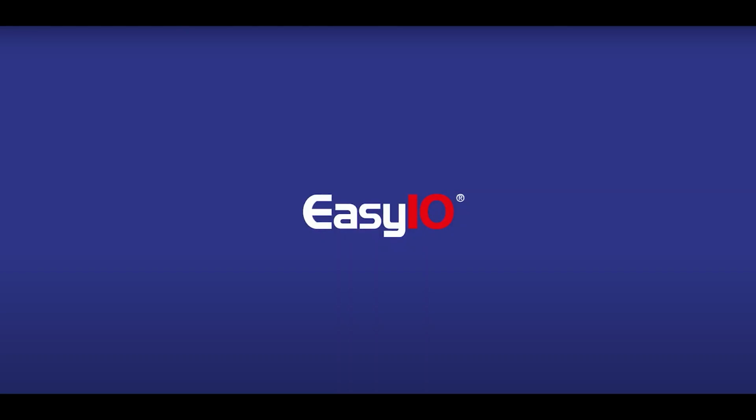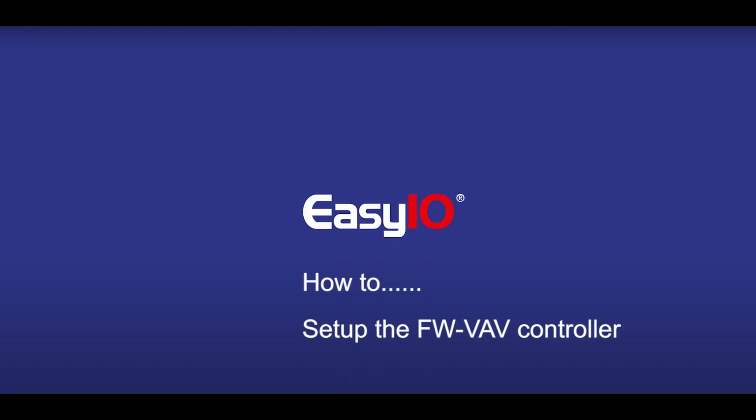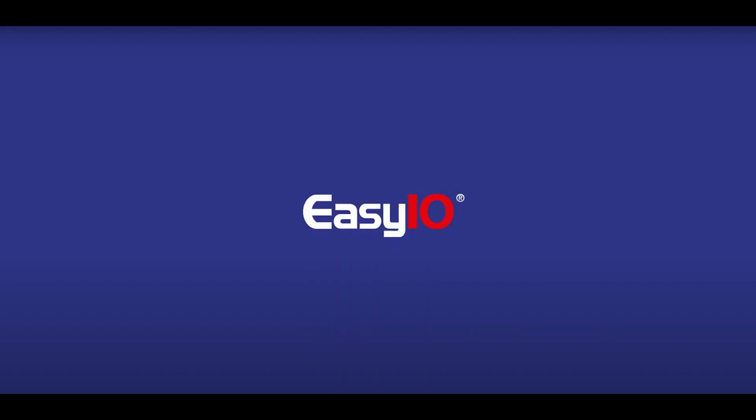Hello, welcome to this EasyIO how-to video. In this video we are going to show you how easy it is to configure the EasyIO FW-VAV controller, just using a browser, without any additional software. All the parameters discussed in this video are directly available on BACnet. The dashboard writes to priority 16, and it's free to configure or edit the dashboard the way you want.